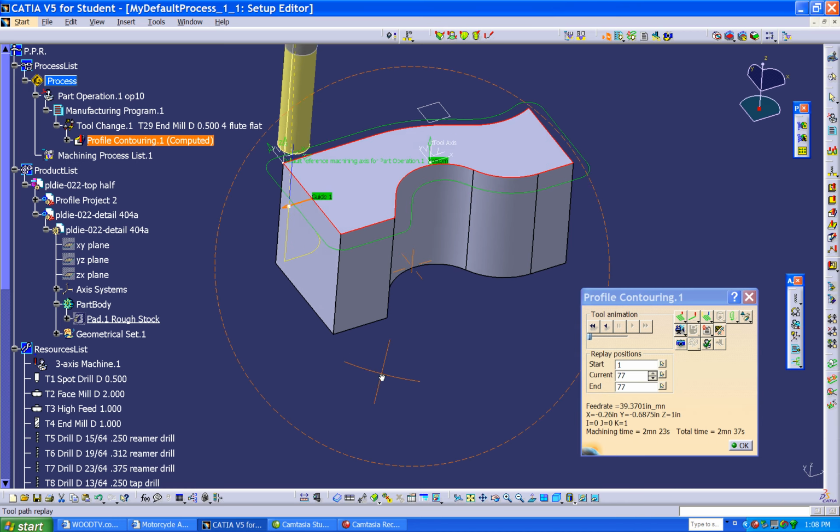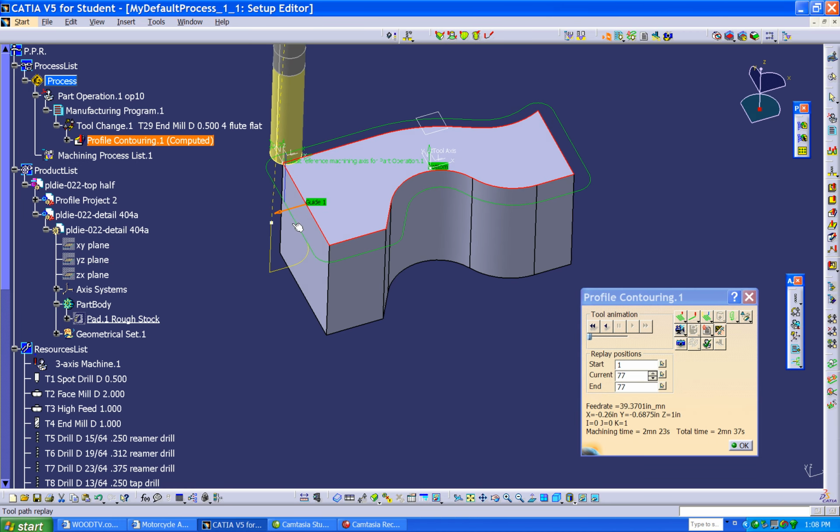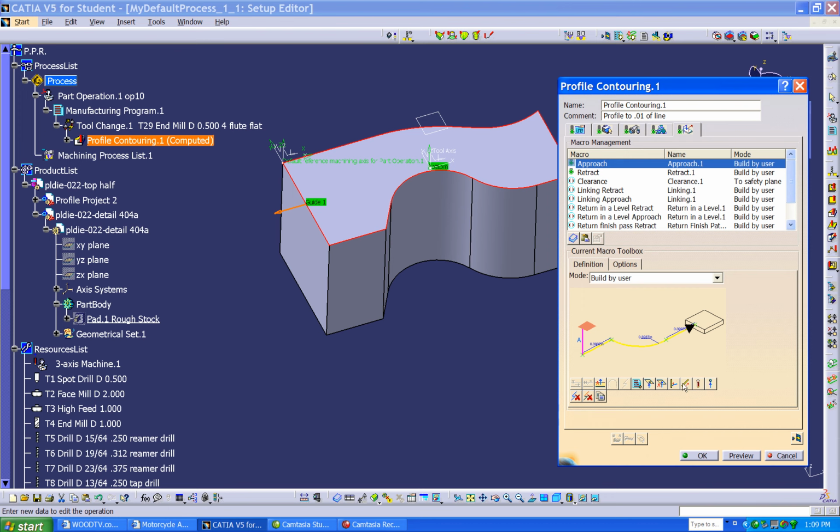Here it is. We've actually taken and extended out our toolpath a little bit. We have a sweep in. We have a vertical line or a straight line move into our arc. And we're up to our safety plane. I like this for several reasons. One, I can turn my cutter comp on right here. I've got a straight line move that's off my workpiece. I sweep into the workpiece, and I'm actually generating somewhat of an overlap in here for it to come right on around.